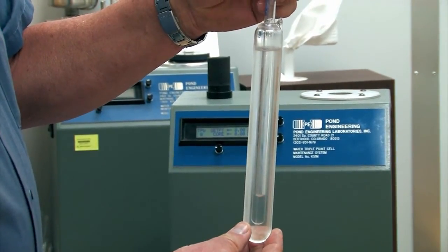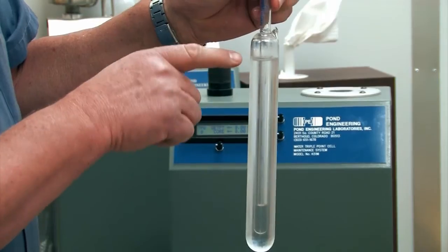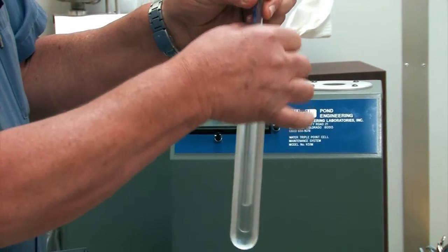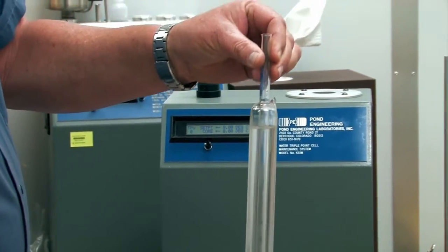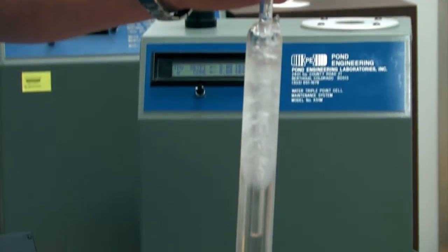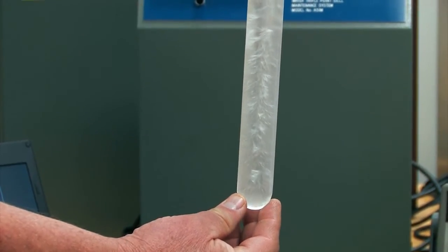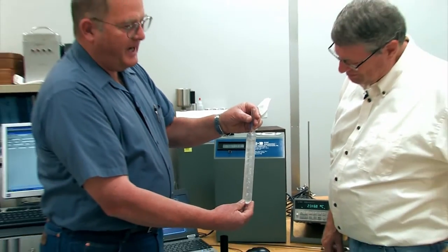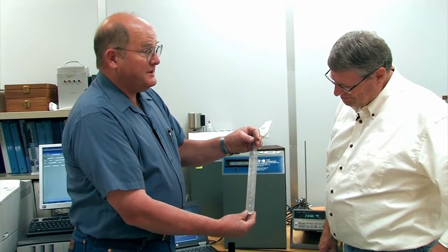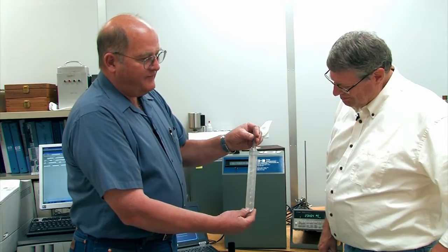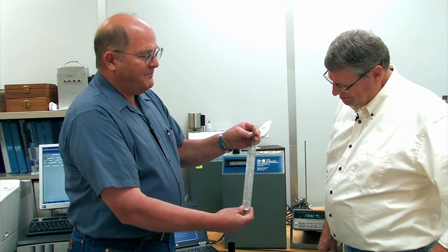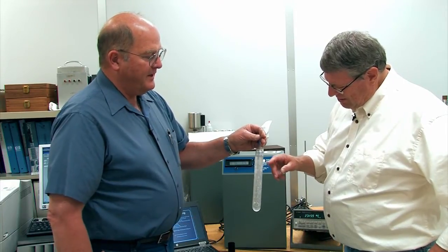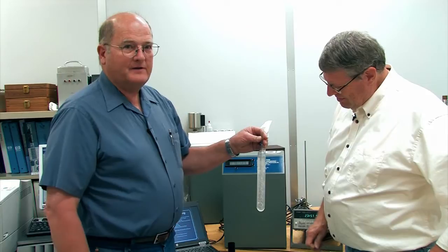So the liquid water in this cell is cooled to approximately 8 degrees below zero. If we agitate that cell by shaking the top of it, a nucleation site will form, one crystal will start, and then those crystals will propagate down the length of the cell. Okay. So I'll hold the bottom of the cell, and we'll agitate it, and it will form ice crystals down the length of the cell. Now look at that. The water inside this cell has now warmed up from approximately 8 degrees below zero to 0.01. The ice has formed, which will now act as a buffer, maintaining that 0.01 C for a long period of time. In this case, approximately 8 hours inside the maintenance system.